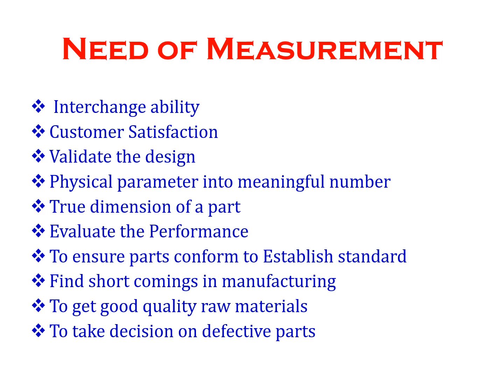Anywhere we can purchase the required spare part and replace the existing worn out spare part, because it is possible only because of the concept called interchangeability. That is, we make the component with the required dimension, accuracy and precision, so that the component can be fitted to any other equipment where a similar component is needed.